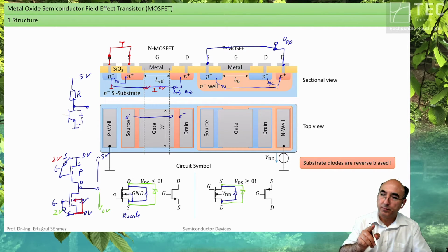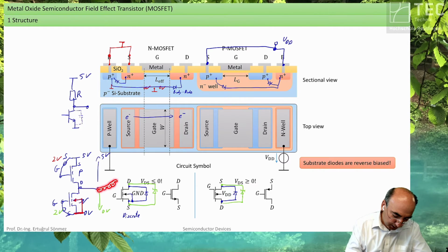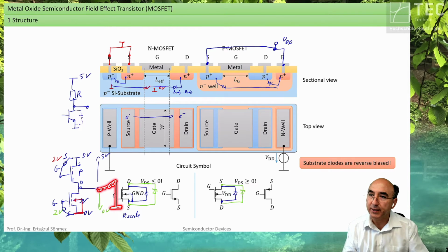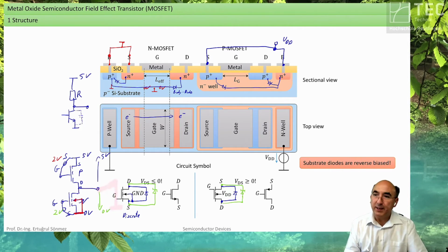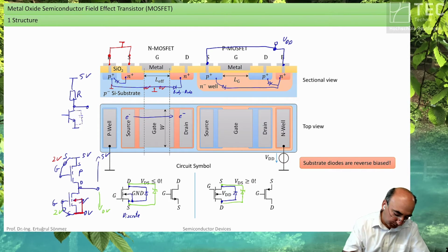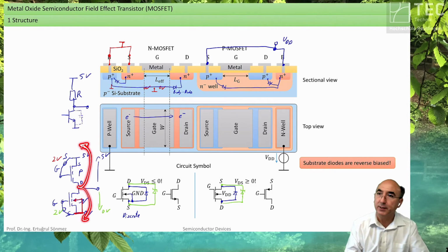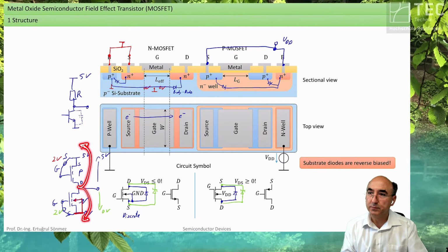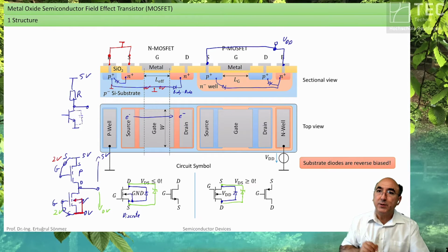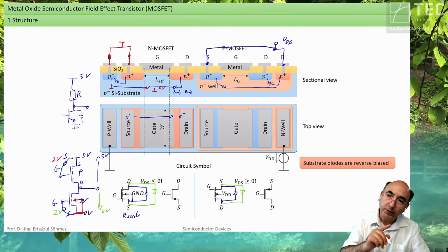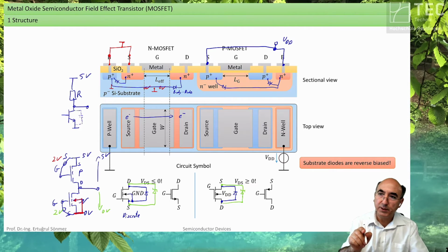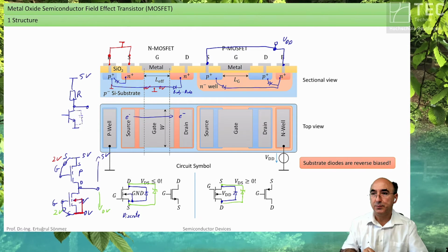Therefore, you have a trouble because in 600 volt applications you have, for instance, an electrical engine. An electrical engine has spiral inductors called the coils in the engine to generate the torque. And these inductors force the potential higher and lower than the supply limits. And therefore, you can't use MOSFETs. You have to use the so-called IGBTs, insulated gate bipolar transistor.